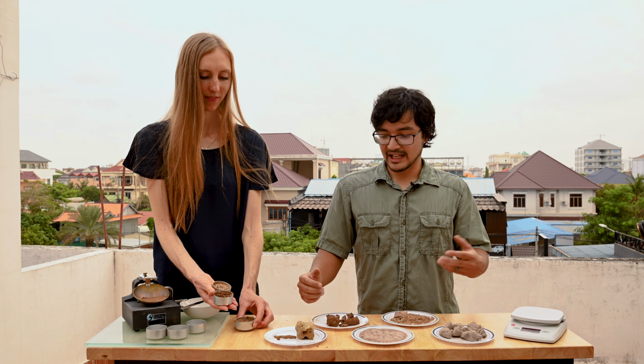So we also have density and consistency, which are used to describe the resistance of a soil to deformation and rupture. This is difficult to measure in the disturbed state that you would be doing in a typical field test if you're doing hand augering or digging, but we will discuss this testing for soil consistency in a future video. Coarse-grained soil would be described by its relative density, which would range from very loose to very dense. And the fine-grained soils are described by consistency, ranging from very soft to hard.